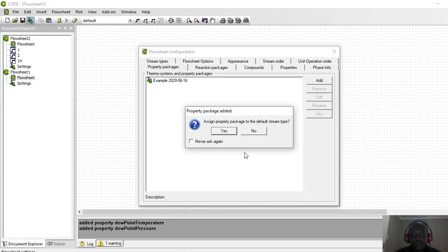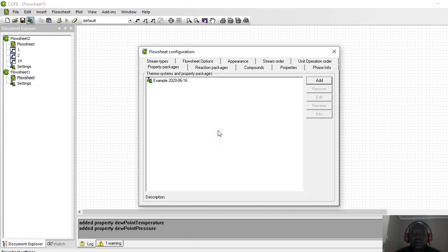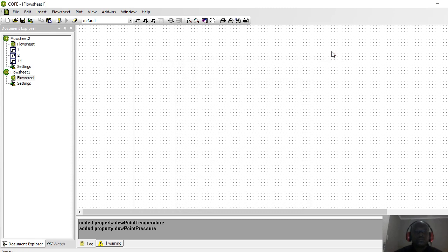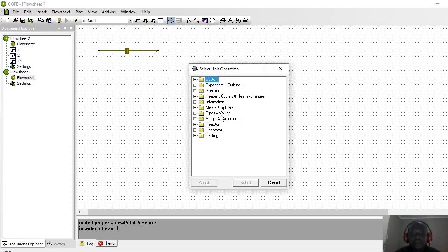Yes, we want to assign it to our streams. Then we're going to start with your input stream of hydrogen. Again, you click on the stream, one click, and then drop it. And then let's compress our stream. As we said, our streams are coming in at 1 bar. So let's compress our stream, pumps and compressors. There's your compressor right there.